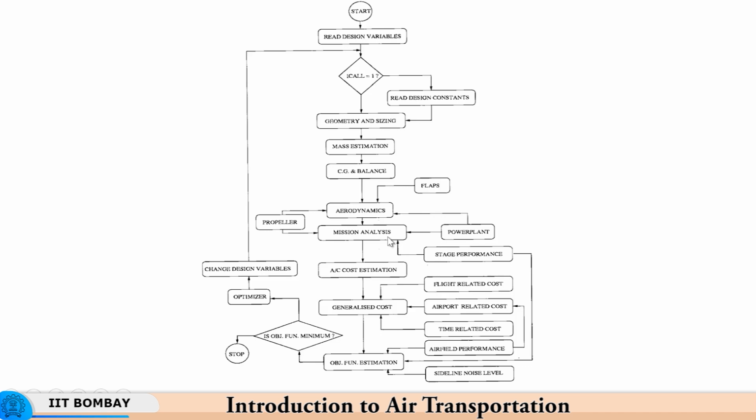Finally, you do mission analysis, and then you can do the cost estimation. When you have the cost estimation of the aircraft, you can do the generalized cost estimation. This estimation will require flight cost, airport cost, time cost. The excess cost is considered a constant number in this study.